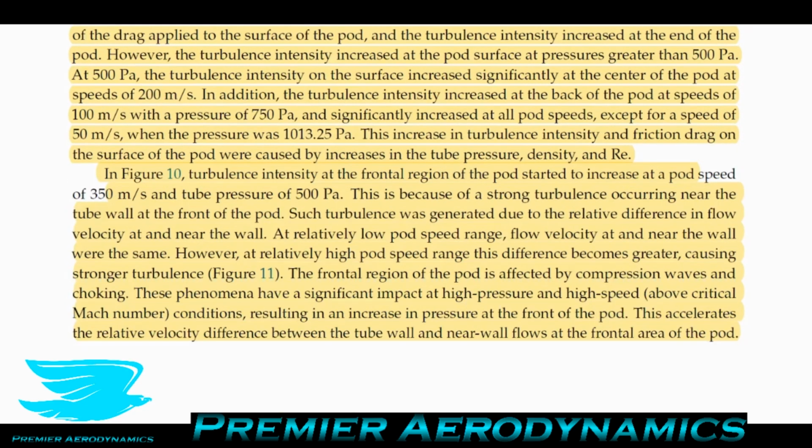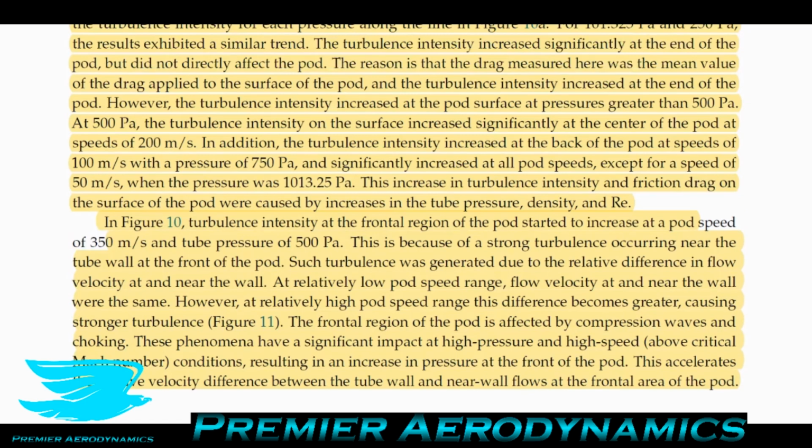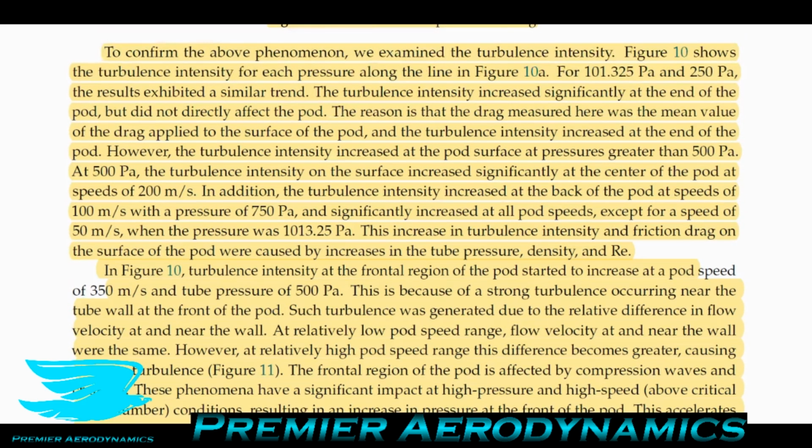So in figure 10, I should just probably cover how turbulence intensity does change things. In the podcast that I mentioned, I go into that as well, but I'll just mention it briefly here. The boundary layer and just the flow in general, its uniformity and behavior is very heavily influenced by the turbulence intensity. So the greater the turbulence intensity level, the lower the velocity you can have and still have a turbulent boundary layer or a turbulent flow.